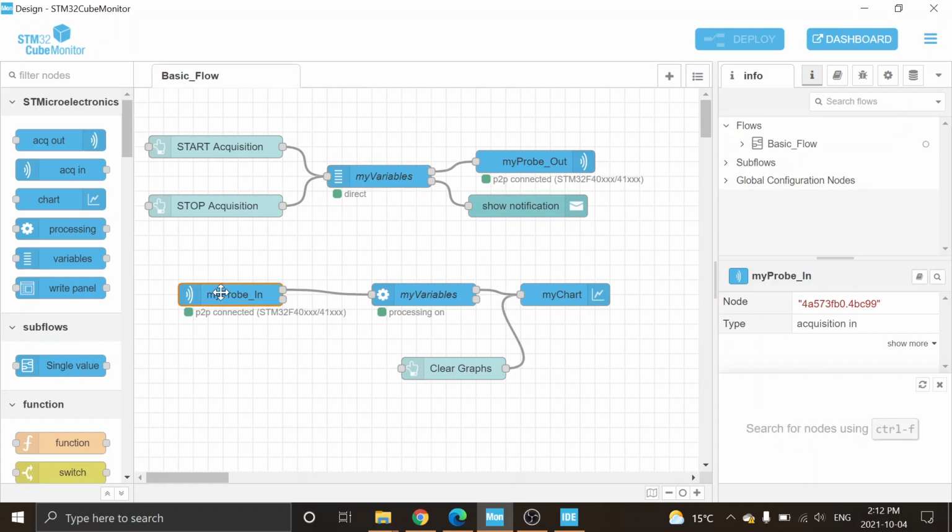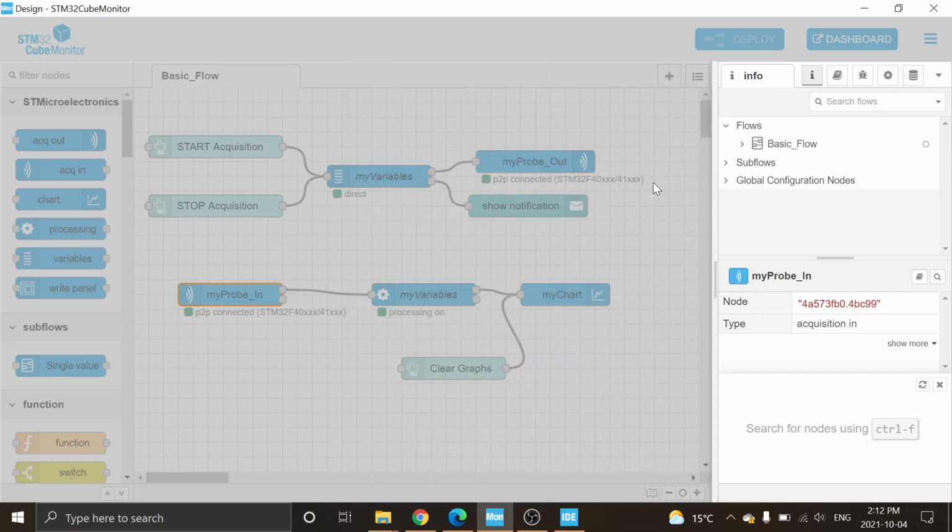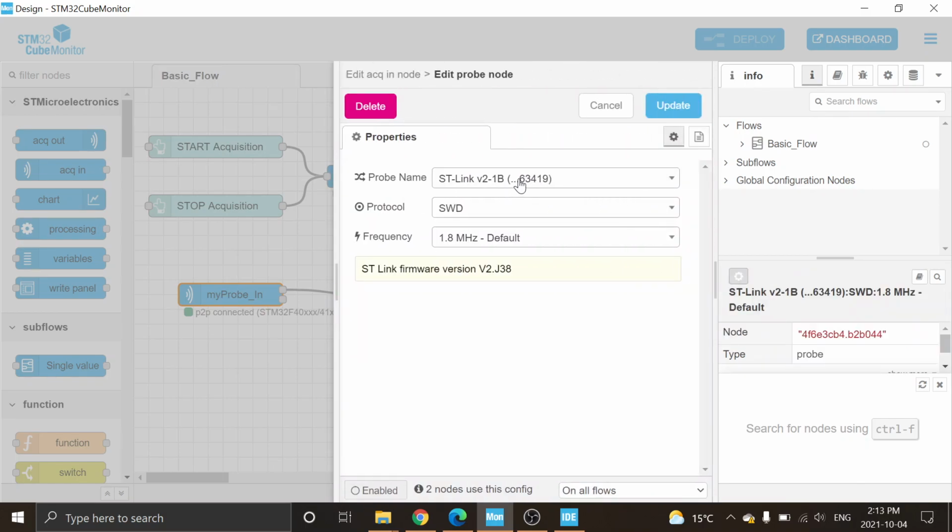And I just went like this, and I double-clicked, and then I said set up, and then I had to go and just say find, and it found my ST link. And it knows what serial number your ST link is versus somebody else's. So if you plug in another board, you have to go and search for it and pick the right module. It'll remember the other ones.